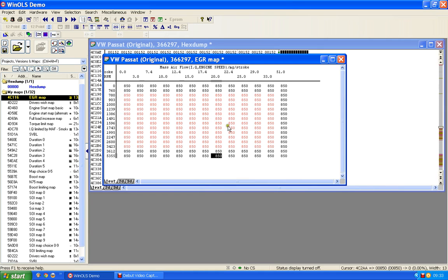Now, from somewhere in the region of 2001, when the PDs were introduced, the ECUs became much cleverer and they began to look to see if these figures here were reasonable. And all being 850 is not reasonable.